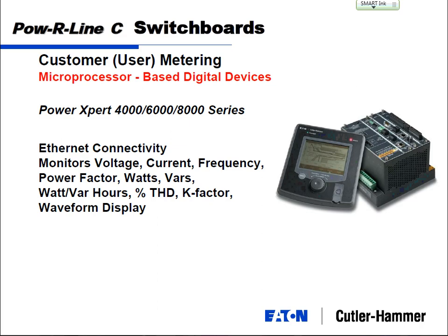And a power quality meter has the ability, more than likely you'll get the same Ethernet connectivity, monitoring your voltage, current, and all the values that go with that. But you also get the ability to have a waveform view. And this particular one, and I can't see it very well, but it comes in two pieces. This meter itself is about like a shoebox, so it's much bigger. And the display then can be mounted anywhere. And you can kind of see on the display a little bit. Same information that's going to be in the web server, but you can see an actual waveform.